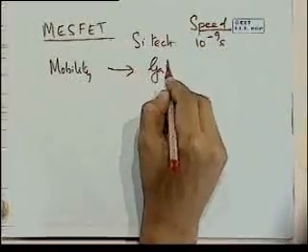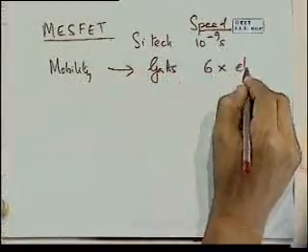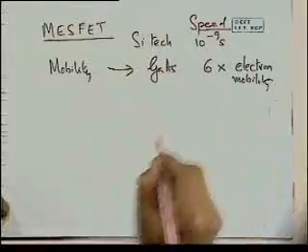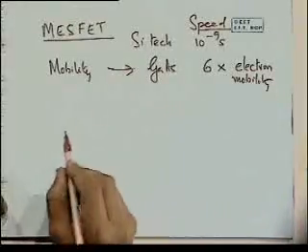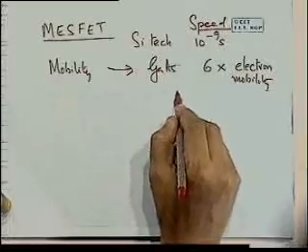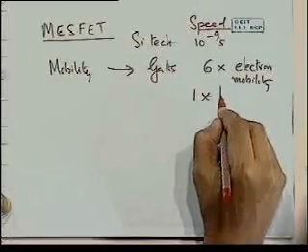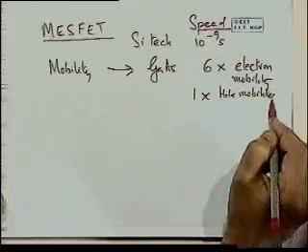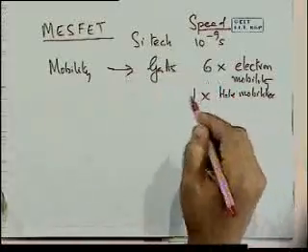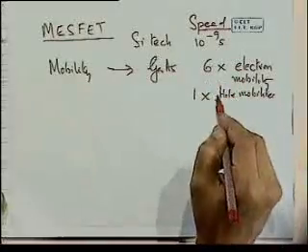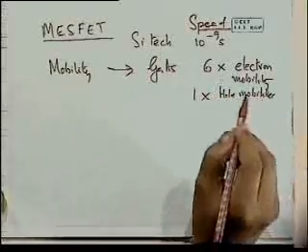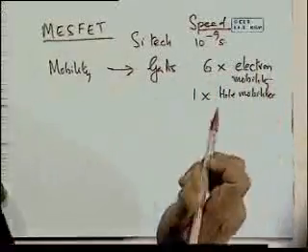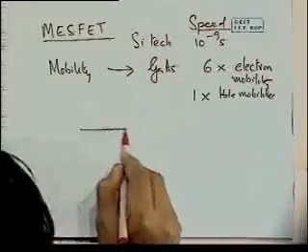And gallium arsenide, it turns out, has got a 6 times higher electron mobility, if you remember some of the numbers that we looked at. So that seems a very promising candidate. The only problem is that the hole mobilities are approximately the same. What that might mean for us in terms of design of a device where we want higher speed is that we should try to make use of only n-type gallium arsenide, because then everything will be running with electrons and we'll make use of the actual high speed. And the device that is used is known as a MESFET.